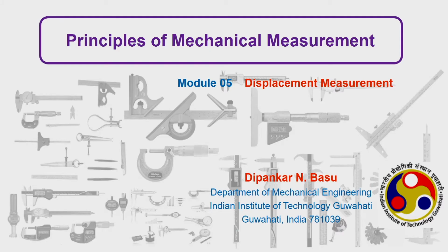We measure the displacement of the mercury column within a capillary tube. So, what we actually measure is a distance. Now, it is a different thing that the scale of distance is given in terms of temperature, so we can directly get a temperature reading, but the fundamental parameter that we are measuring there is displacement, or the change in the length of the mercury column.